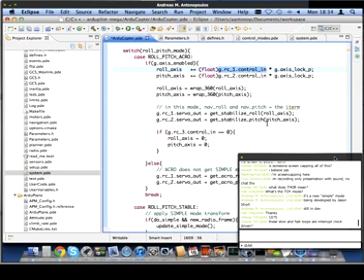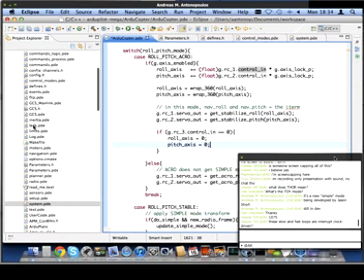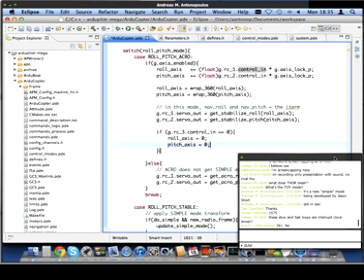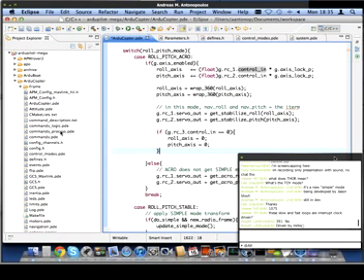checking, is it acro mode? Is the roll pitch currently the acro mode or not? If it is, then what it needs to do is first look at the control inputs from the pilot, which are sitting in these g.rc_control_in. It needs to decode those, right? And it needs to then send them into the PID controllers. But actually, it doesn't go directly into the PID controllers. What it does instead is it calls these functions like get_stabilize_roll, which are inside of attitude.pde.